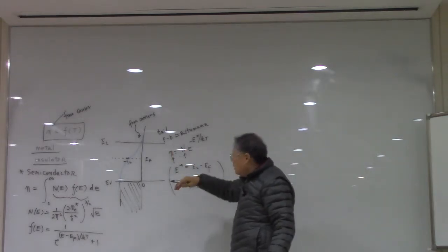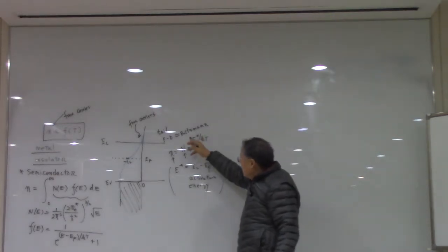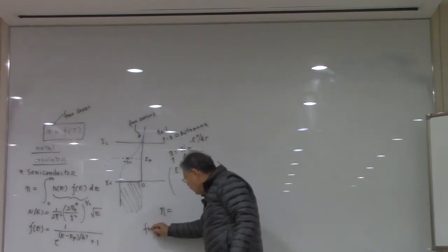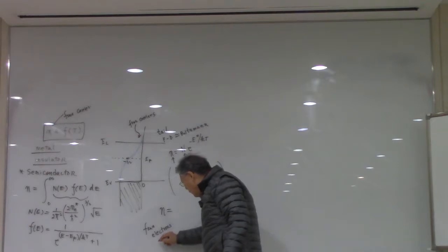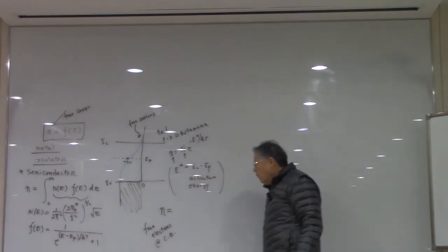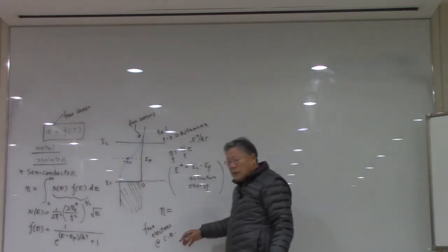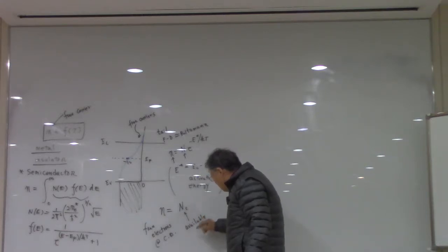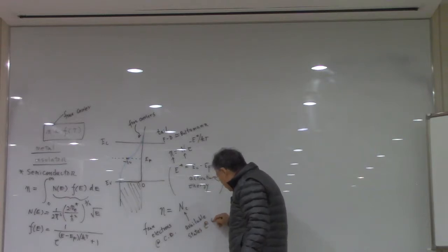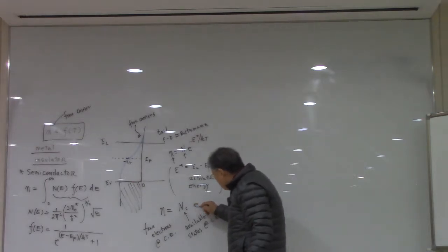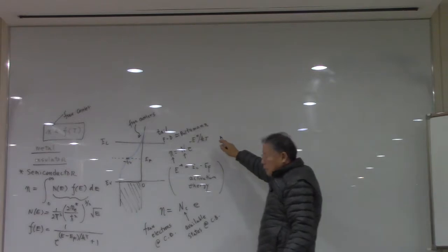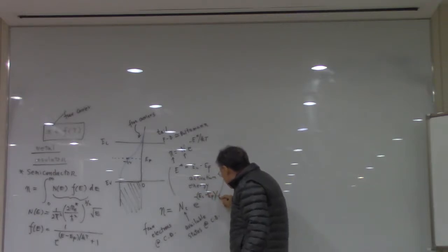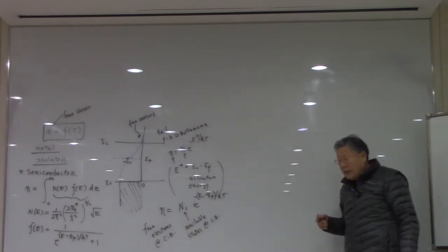So if the Fermi-Dirac statistics can be approximated to be the Boltzmann statistics, then we are going to say the number of free electrons at the conduction band is going to be some available states at the conduction band multiplied by the Boltzmann statistics, which is e to the minus (E_C minus E_F) as an activation energy over kT. This is the equation that we want to derive.